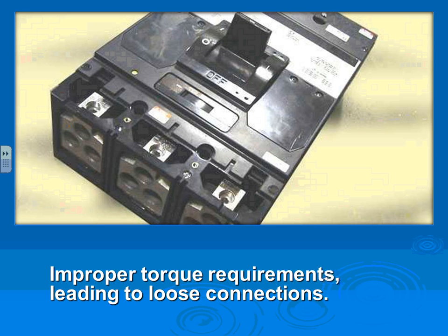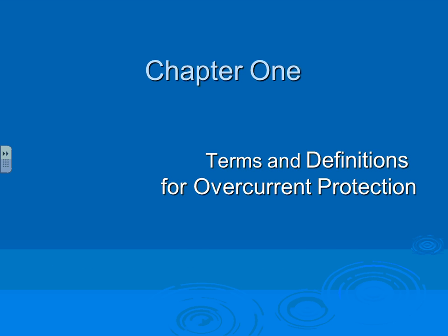So you say, Chad, how are we going to maintain that torque and how often do we need to torque them? That's where this document becomes really good and handy. It will tell you how often you have to go torque these lugs on the circuit breakers and so forth. NFPA 70B.